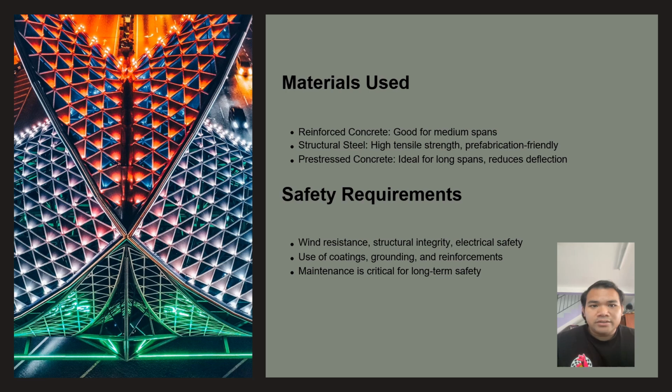For the materials used, first we use reinforced concrete, because it is good for medium spans. Second, we use structural steel. It has high tensile strength and is prefabrication friendly. And lastly, we use pre-stressed concrete because it is ideal for long spans and reduces the deflection.